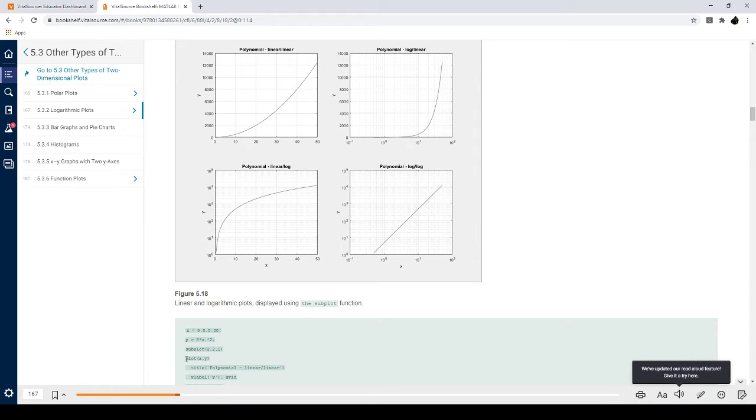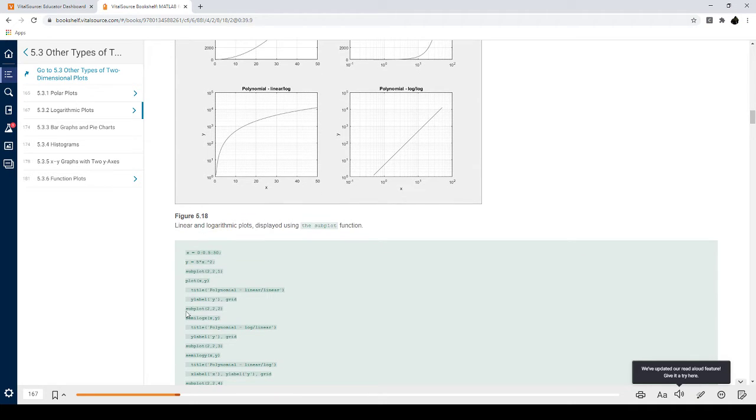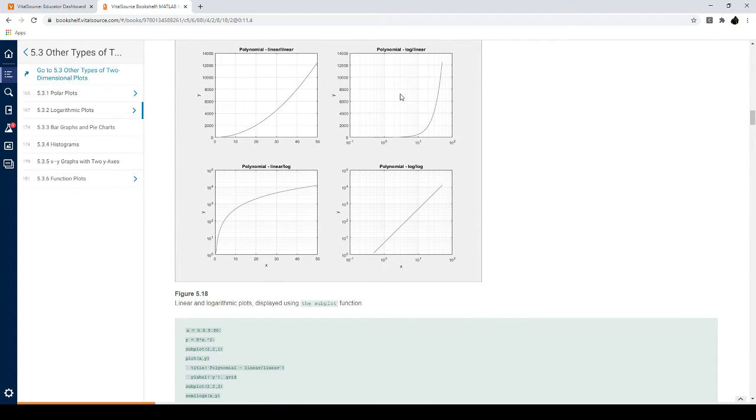Right after that subplot command, they hit plot(x,y), which plotted this function at this location. So that's why this first one ends up here. Then they added a title and everything to it, and they added the grid. On the next one, it goes 222, because they did the exact same thing they did for 1, except they subplotted it in the second location, which is right here.